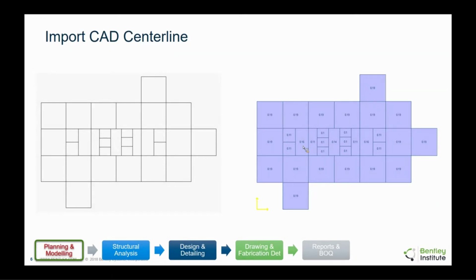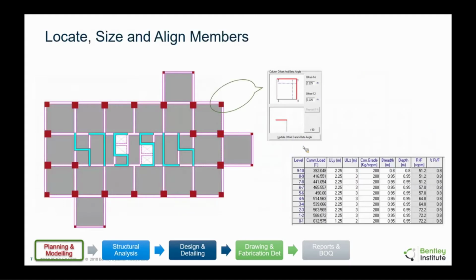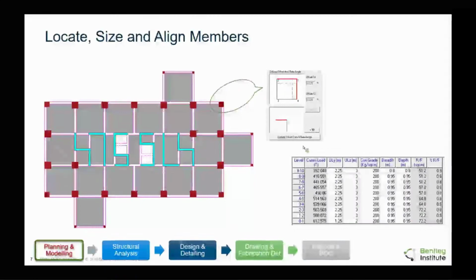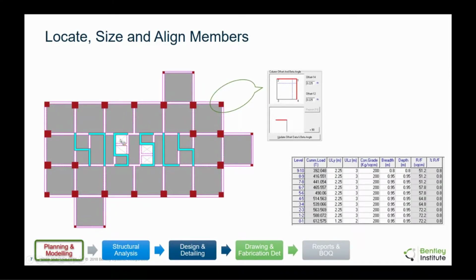And then on this view, we've got a lot of automation tools. You click a button, it will suggest potential member sizes and locations. You click a button, it will tell you how to orient them and so on. You get auto beams, auto columns, a lot of those automated tools, and you can translate this center line into an actual layout which looks something like this. Now this is a tall structure, a 37-story structure, and this is the current iteration that the engineer is working with. So what you can see here on the screen is there are of course beams, slabs, columns, shear walls, there are cutouts. You'll find that this projection here is local, and consequently the columns are very small. The corner columns are smaller, inner are larger, and so on.